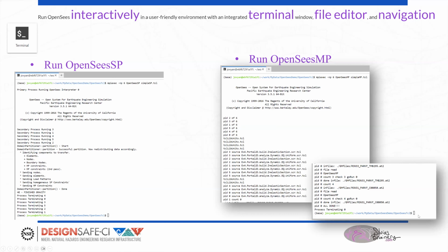Now, remember the number of cores, you have a certain amount of memory, and so you don't want to use up all the cores. If you have a memory intensive model, you might want to use fewer cores and therefore dedicate more memory to each core, rather than saying, oh yeah, I'll just use all the cores that I have available. So that requires a little bit of thinking and planning.